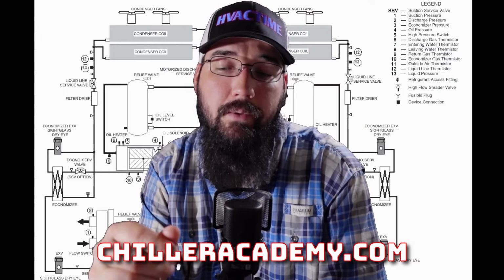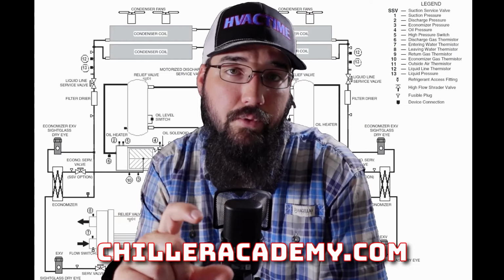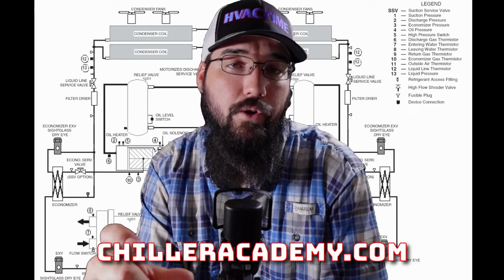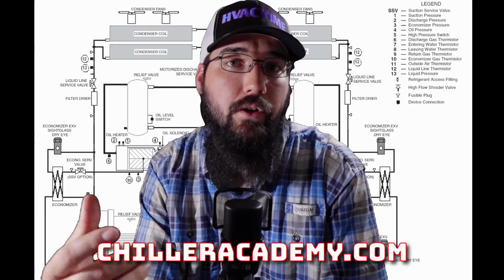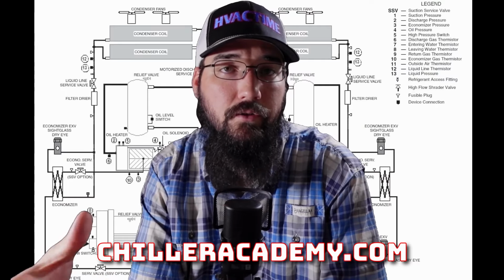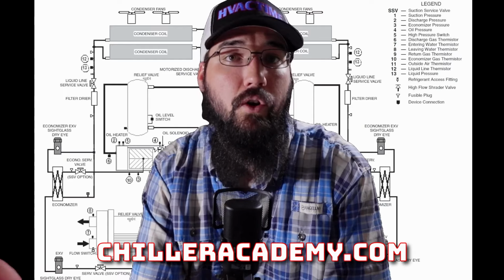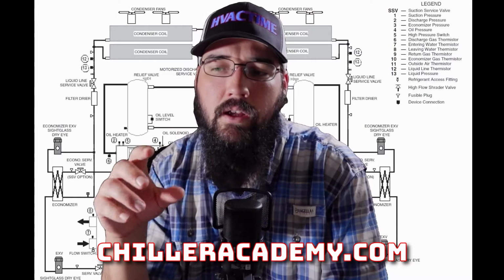The current limit is there to make sure that, given certain conditions, our compressor is not able to overload what our motor is capable of keeping up with from a torque perspective, which increases our current draw on the stator in order to keep up with that amount of work being done. I hope that makes sense, and we'll probably need to talk about this some more as we go.